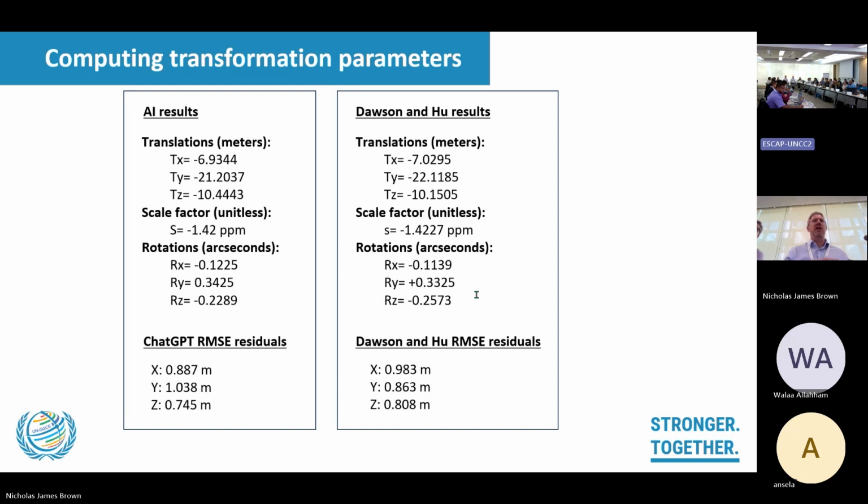There's certain things that the APREF community can't do for you because they only deal with the regional component. Those sort of decisions about plate motion models, I think they fall more into the national category where you make a choice and then you do the work. It's not to say that people within APREF can't provide you with assistance, but I think that decision needs to be made at a national scale rather than having someone else develop that kind of model for your country.